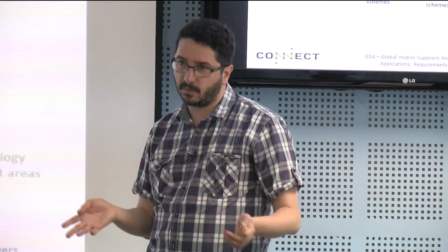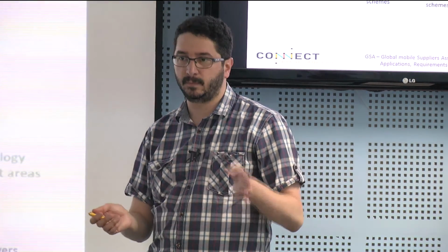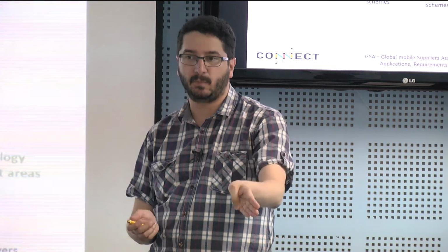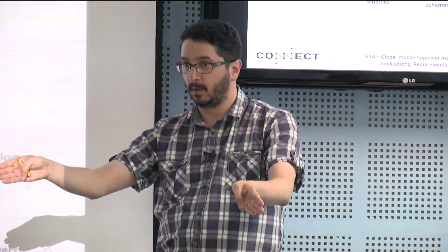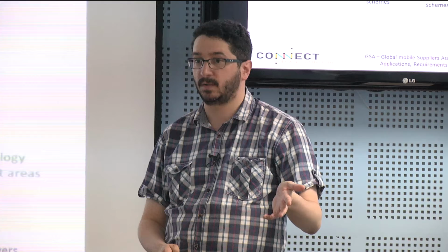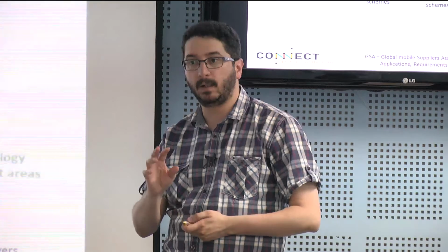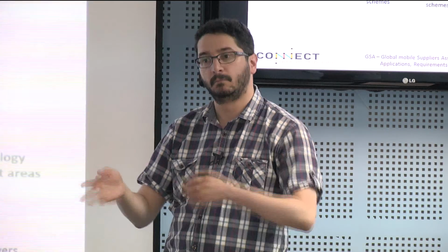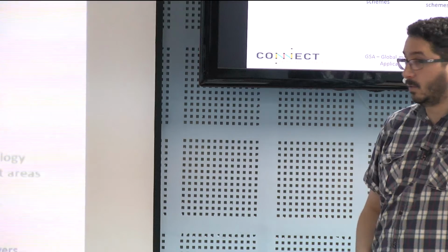In terms of massive MIMO, there are a few benefits, and one of them is you can reuse the spectrum better because you're very directional. If I transmit to my user in one direction, I will not disturb another user, so I can create another beam, and potentially could have all the users using all the spectrum. So you don't need frequency division multiple access anymore. That boosts the capacity. Energy efficiency comes from the array gain, which is, if you have a very large array, you have a very large SNR gain. Those are 2 examples. There are more. So there are good reasons to do work in new coding schemes.